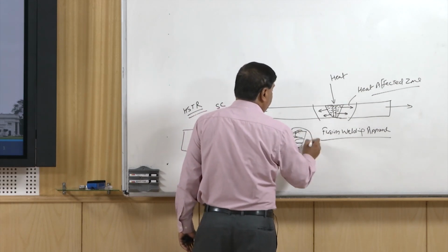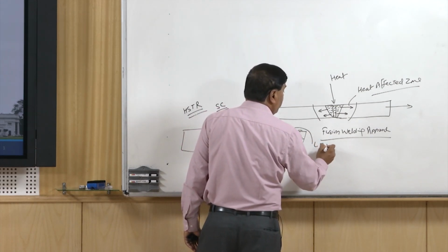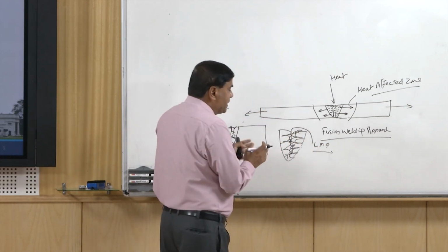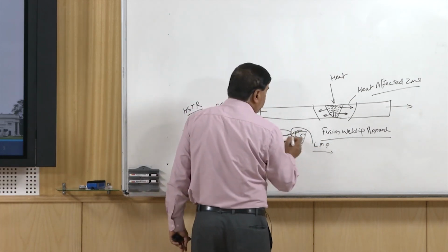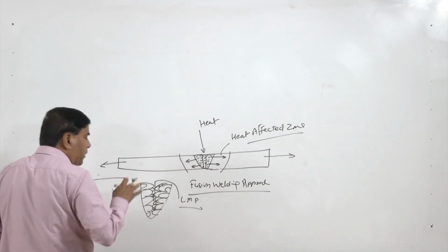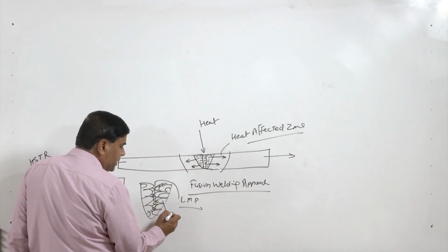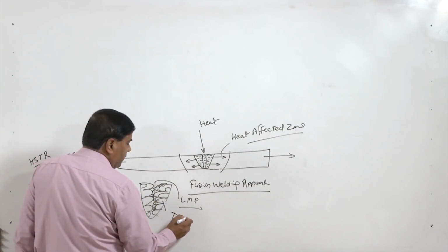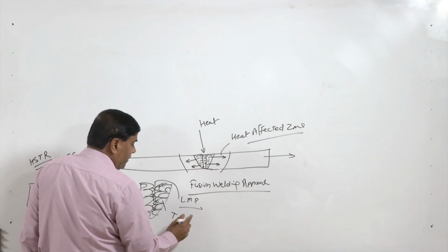Low melting point phases accumulate at the center, and in the meantime the solidified portion, when it cools down to lower temperatures, develops tensile residual stresses.